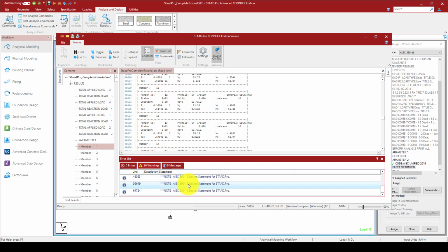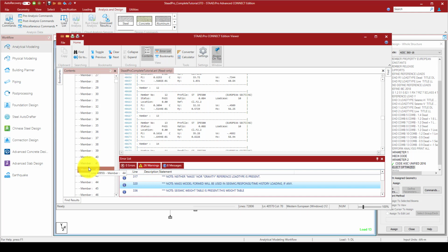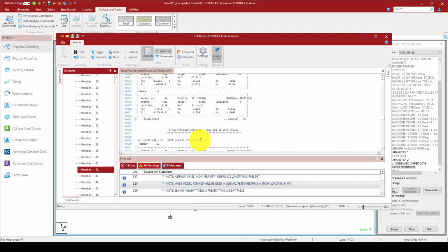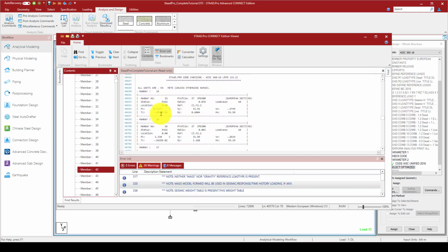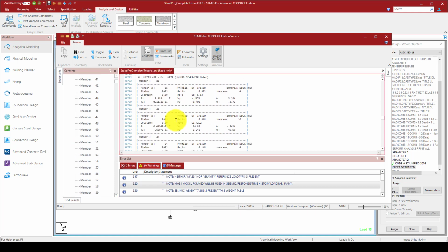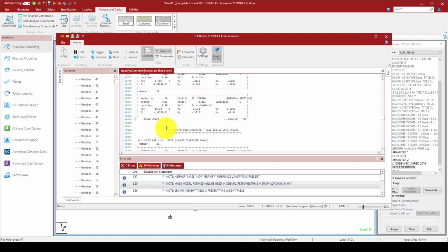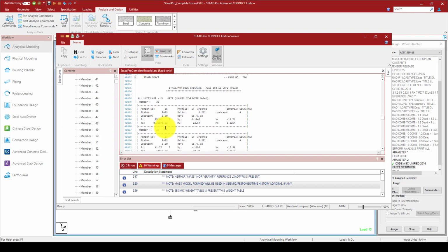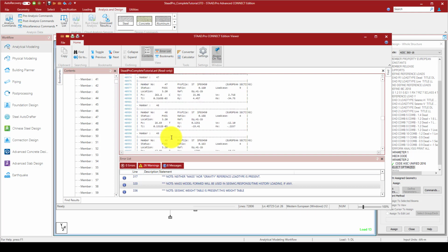This is one problem during the creating of the bracing. We have divided the beam into two parts, so there is some small statement, and you can see the statement is exactly the same as that one. Now we can check the entire members, and this member is passed. Yeah, passed. We don't have any failing members.